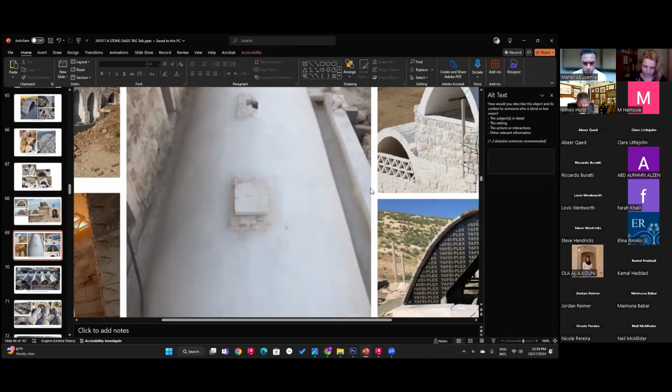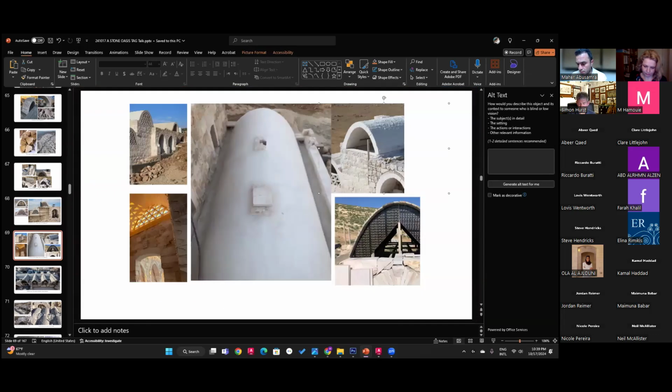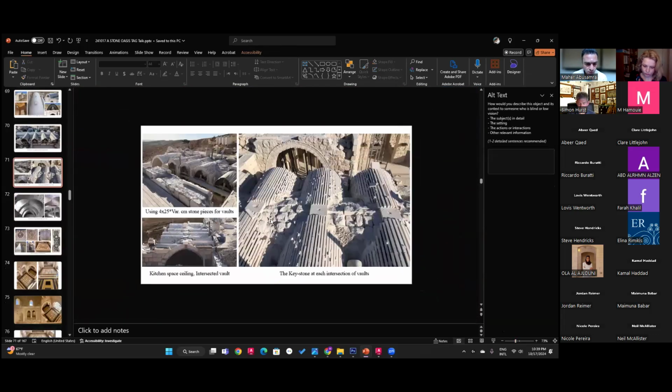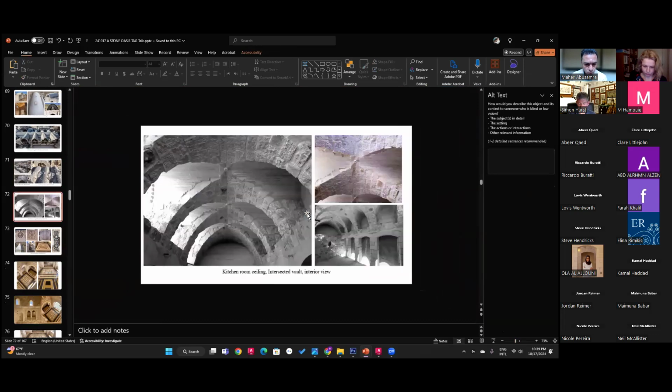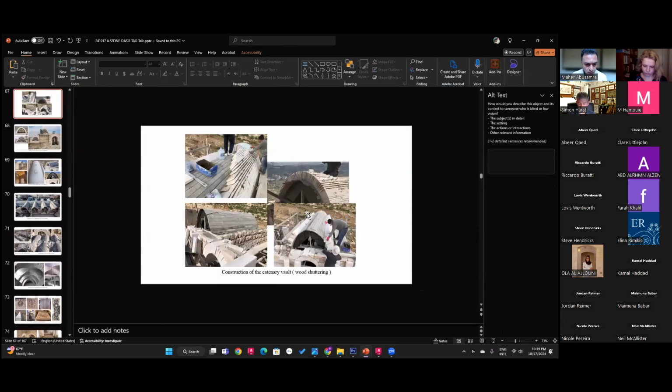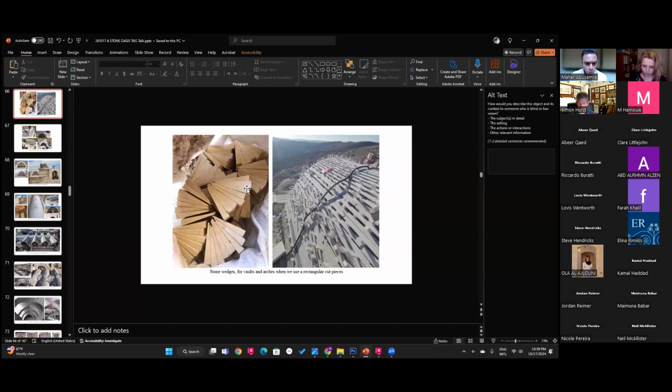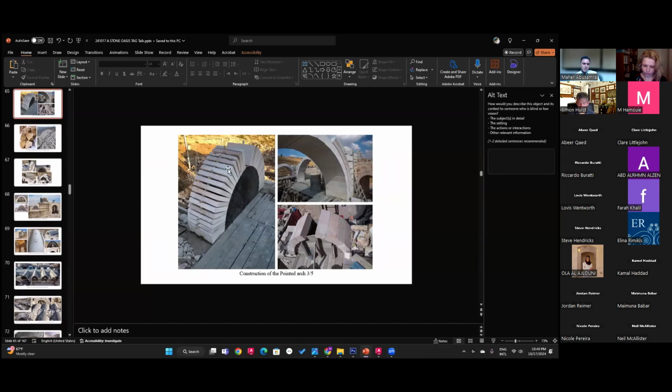So we cut these stone wedges and started using them here. It's easier. For each stone, you put one or two pieces of that stone-edge wedges, and this one comes very, very easy. We have a lot of 5 centimeter small pieces that in general you would throw away from this stone. So we put a guide on the table saw and cut those wedges, and it's easy to use them. So you have to find yourself the easier solution while you are building, by trial and error each time.